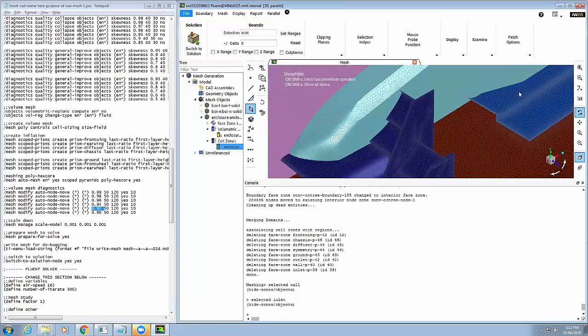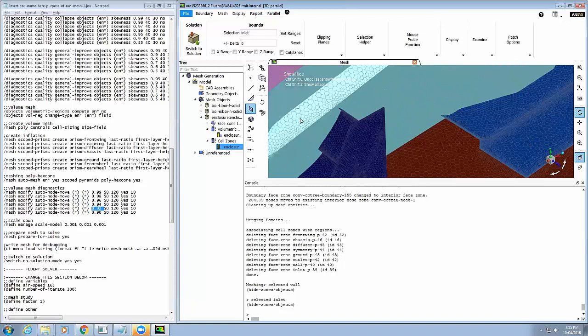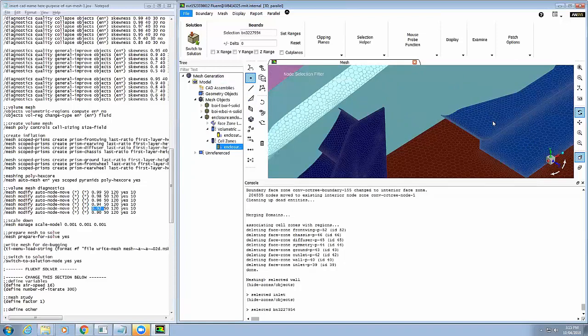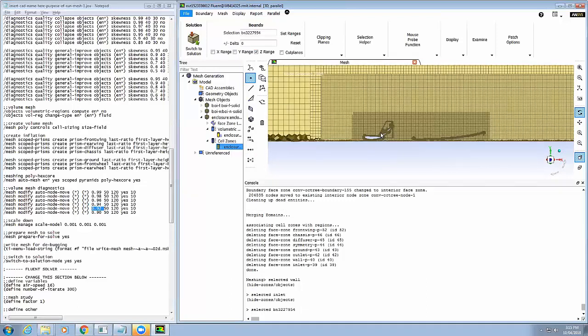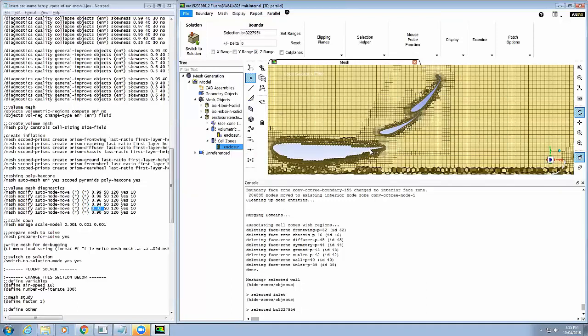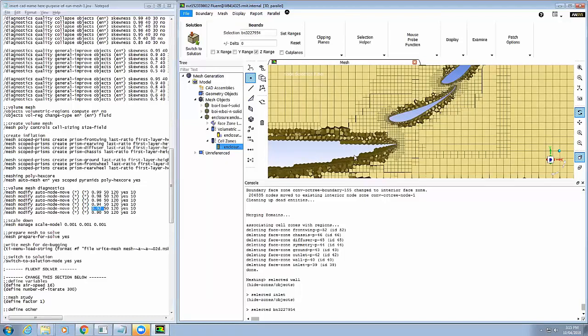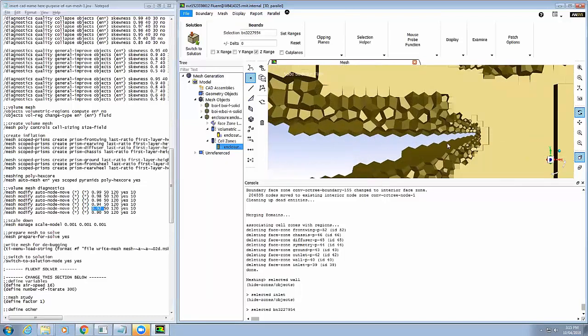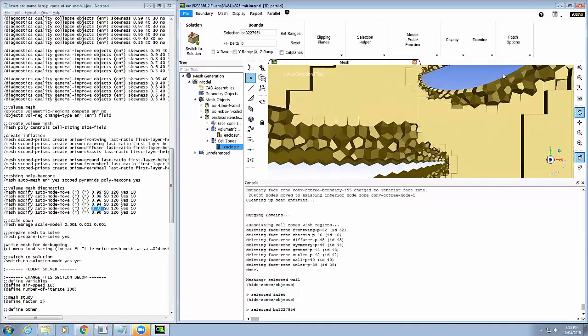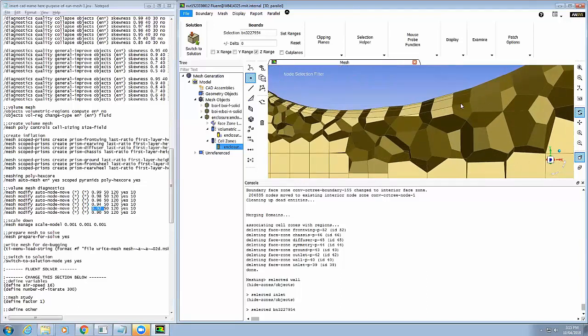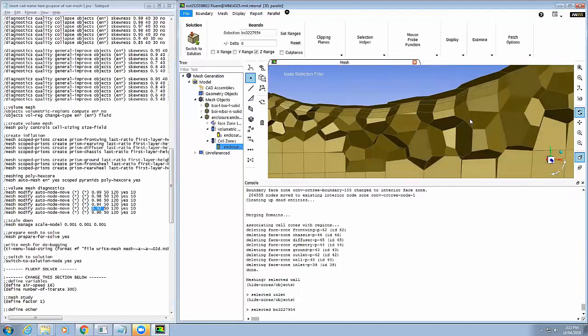If I select, say this flat surface here, around here-ish, right, I can go, I want to see Z values, right click, and I want to see Z in range. Just orientate myself properly, and when you go closer in, you can see poly layers and all your other layers in between as well, right? Right. See also, where's it, your front wing? Can you see? Oh, that's a, is that inflation? Sorry? Is that inflation? Okay, I see it. Yes, you can kind of see 3 layers of inflation there because you see the layers, right? And it comes out there.